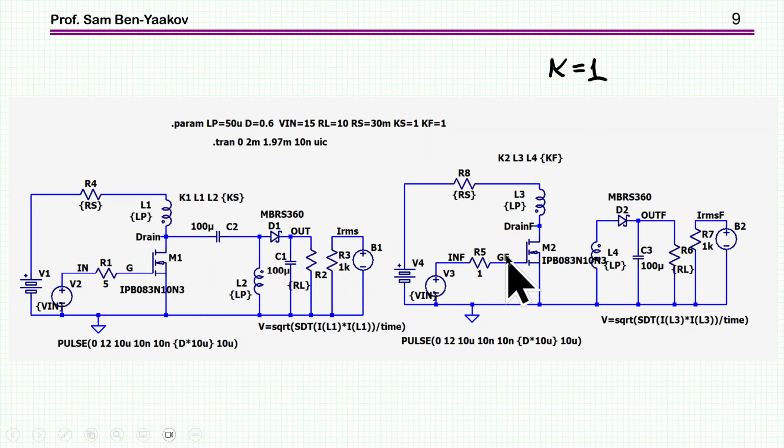And then we have a Flyback, which is very similar, except that there is no capacitor, of course. I've used the same ground, doesn't matter. And I'm comparing now the two for the ideal case in which the coupling coefficient is 1. I've made this capacitor fairly large, which is not realistic. I'll talk about it a little bit later on, what happens when the capacitor is smaller. So this is a comparison between these two converters for ideal coupling.